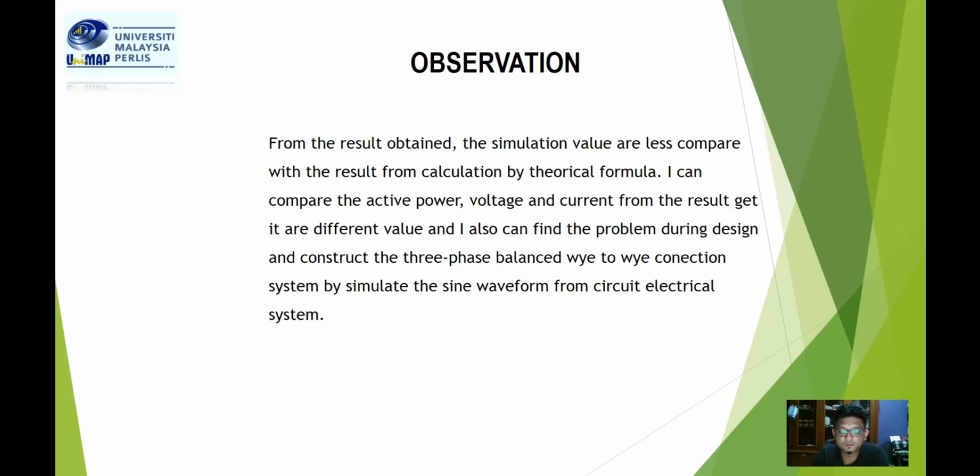I must understand the two-wattmeter method and the conventional method. To prove both methods, I get a lower power factor, 0.977, compared with 0.993. In the PSIM simulation software, the system shows that the result has transmission loss and voltage drop effect from the impedance components in the circuit.